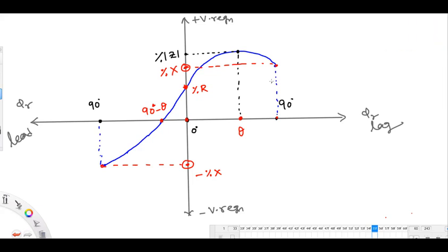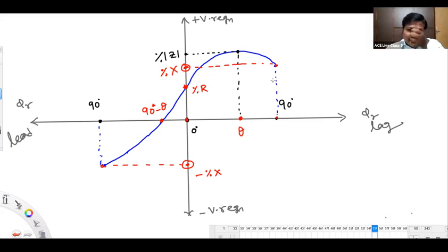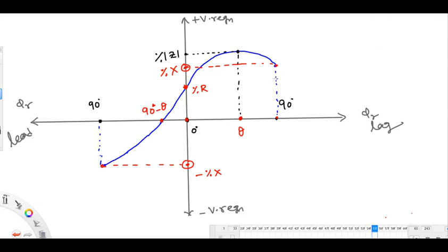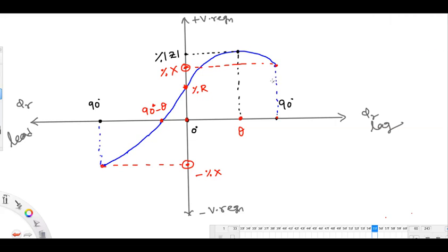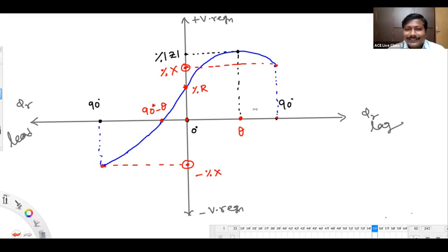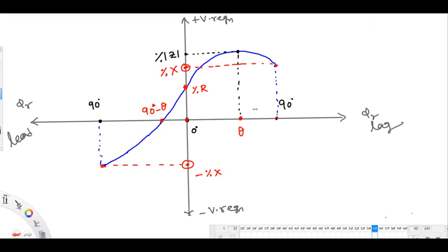Okay, sir. Don't say transmission lines are in delta or star. Those are just 3 wires. In case of windings only, you will say it is star or delta. I mean, depending on our requirement, we modify the connection, sir. No. Again, you are saying connection. I mean configuration, star ungrounded.